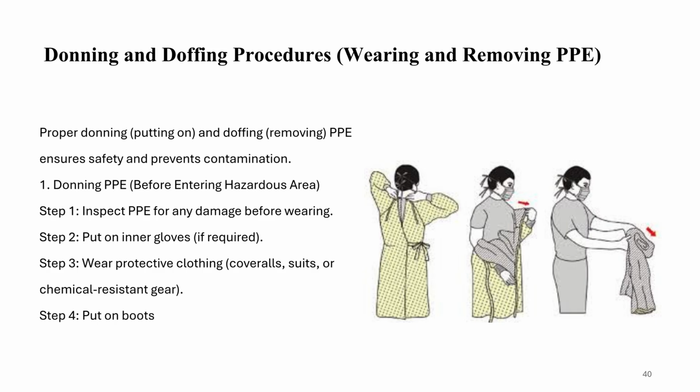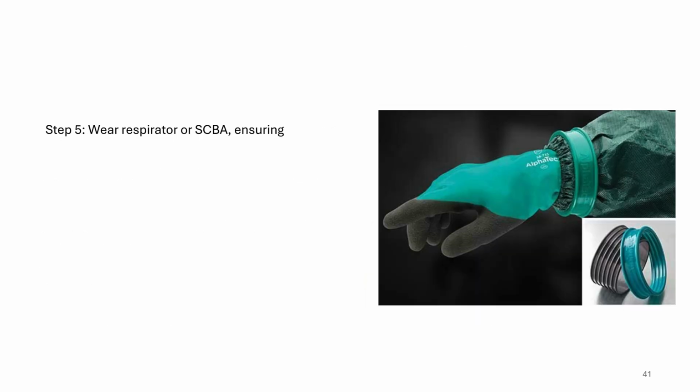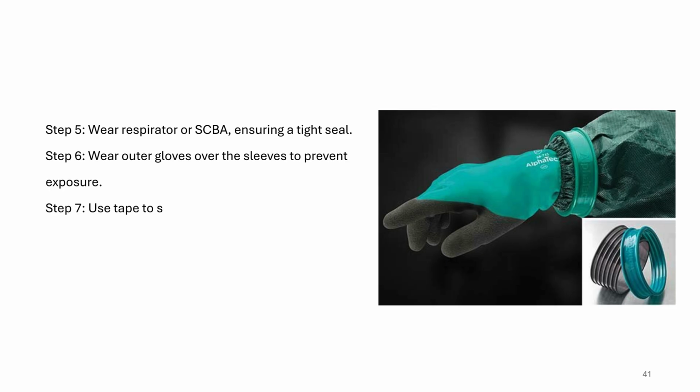Step 3. Wear protective clothing, coveralls, suits, or chemical-resistant gear. Step 4. Put on boots. Cover pant legs inside boots. Step 5. Wear respirator or SCBA, ensuring a tight seal. Step 6. Wear outer gloves over the sleeves to prevent exposure.